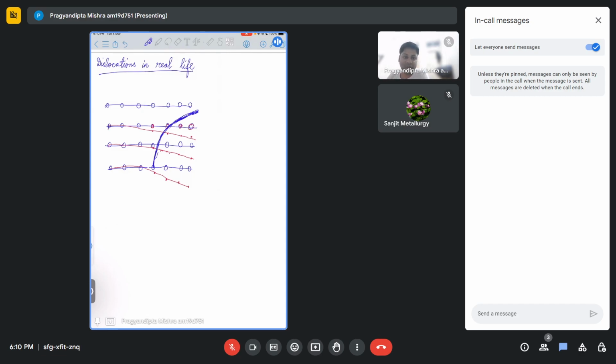Depending on what kind of angle it forms, we can classify it as screw dislocation, edge dislocation, or having characteristics in between screw and edge. So at this point, let's say the Burgers vector for this dislocation is always downwards, or the slip vector.